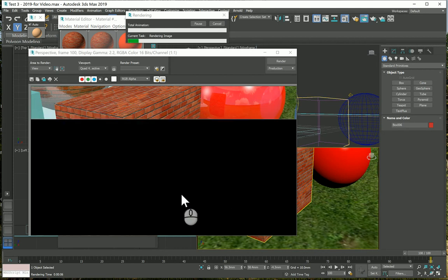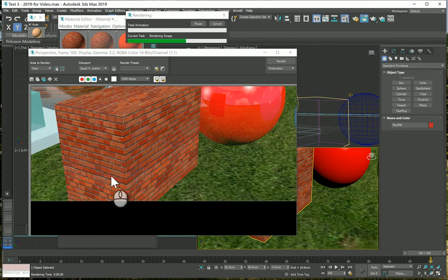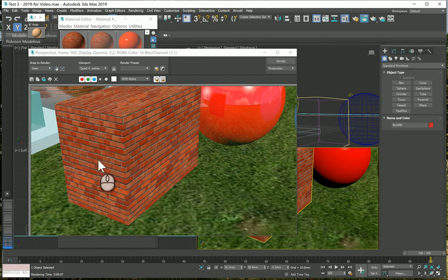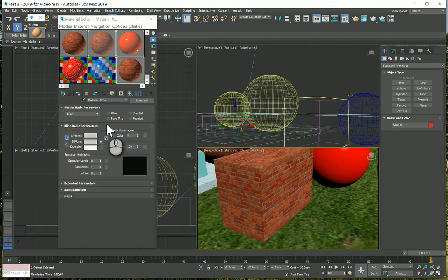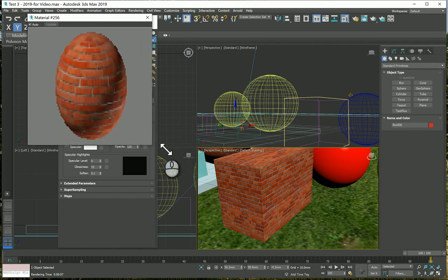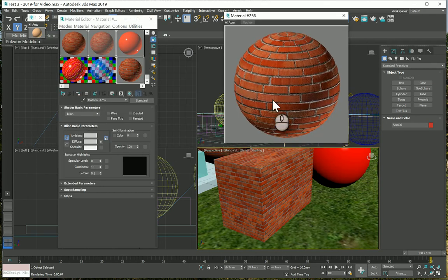Now you will probably start noticing that the bump is getting better, and the whitish parts look like they go inside, and the joints are more realistic because they are lower, or more recessed into the surface, compared to the bricks just going up against the basic surface. So this is just an illusion of 3D. If I double click on that and increase it, don't increase it too much. If you don't have a good VGA, you'll see that the whitish parts are just going down into the sphere. That's the effect of the bump.